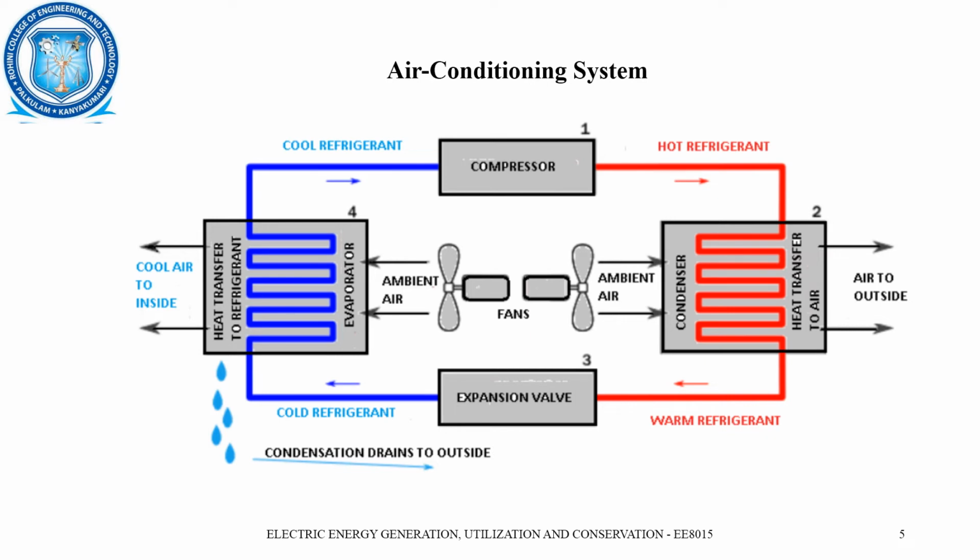This warm refrigerant is then sent to the expansion valve, where the pressure is getting reduced, as the temperature has already been reduced. In the expansion valve we have capillary tubes through which, when a small amount of refrigerant is passed, the pressure will be automatically reduced. Now this refrigerant of reduced temperature as well as reduced pressure will be called the cold refrigerant. This cold refrigerant is then sent to the evaporator coil.